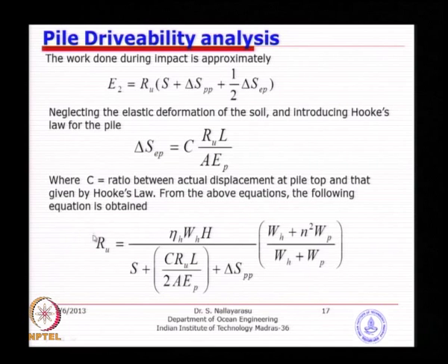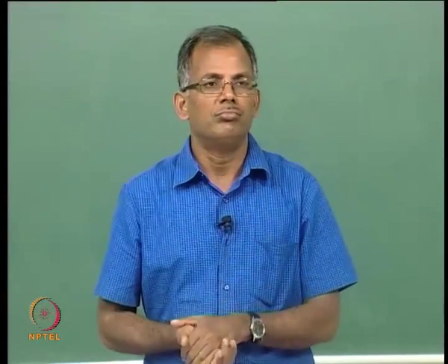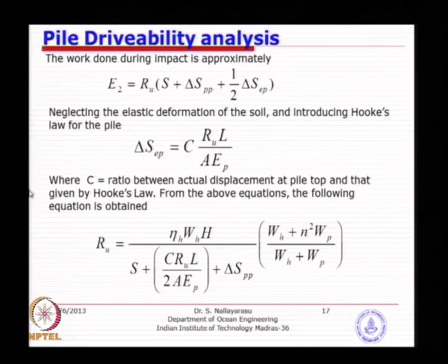You know the resistance calculated by you using your soil mechanics calculation during driving. This is the estimated resistance, and I want to find out what hammer size is required. So, I can keep these 2 parameters separately, and historically I would like to restrict my set value to 20 mm. Then I can substitute back. I know the value of resistance, I know the value of the set I want for the final driving. Then I can calculate that I require a hammer of this height and this weight.